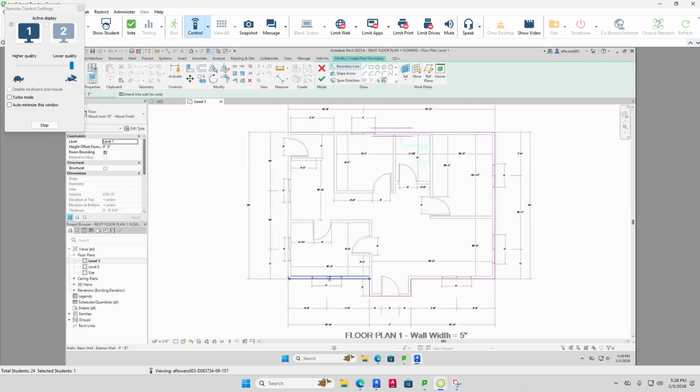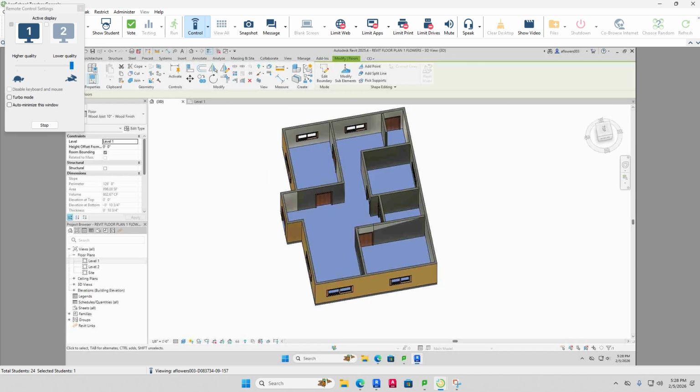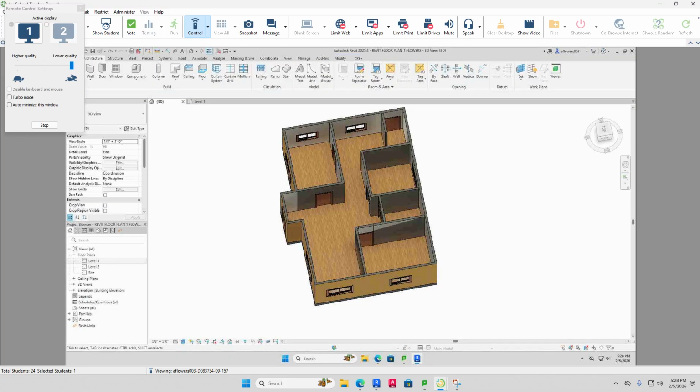And notice what we're not doing is we're not creating an opening for the doors. The doors create their own opening. Perfect. Then hit your 3D view there, Alan. All right, then just click outside of the building to release that because right now the floor is highlighted. There you go. There's your wood finish. All right, looks good.